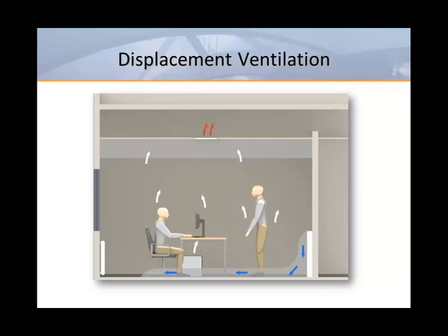In our industry, the word stratification often carries a negative connotation, but that's not really fair. So long as the temperature gradient in the stratification zone isn't excessive, we should achieve comfort in the occupied zone. Now that we know what displacement is, let's look at how it works.